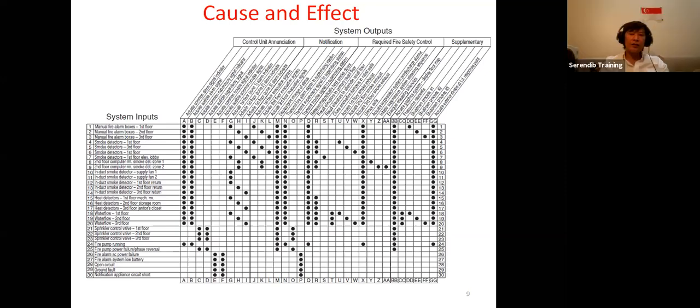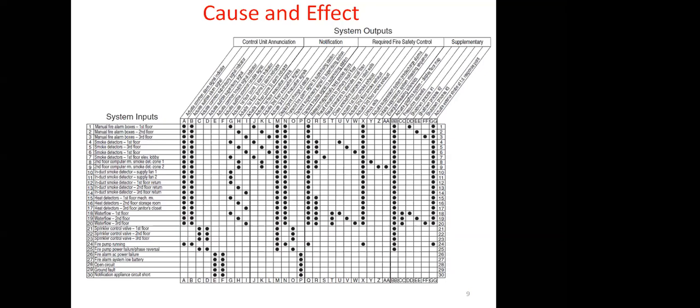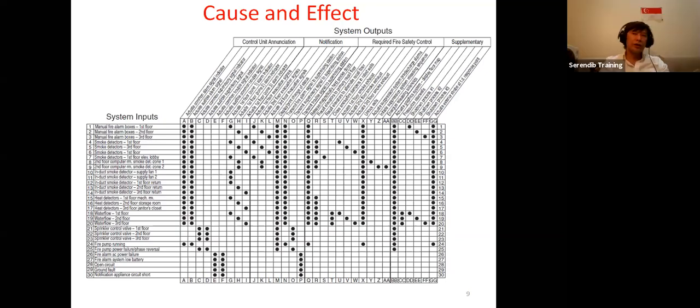What is HSSD? High sensitivity smoke detector, aspiration system, air sampling system. So the enclosure, electrical panels, by NFPA, you don't need to have a separate aspirated system in the electrical enclosure. But if you are going to have that arrangement, and that enclosure has its own detection system, then again, this is up to the fire engineer to decide whether that detection will be interfaced with the detector inside that electrical room.